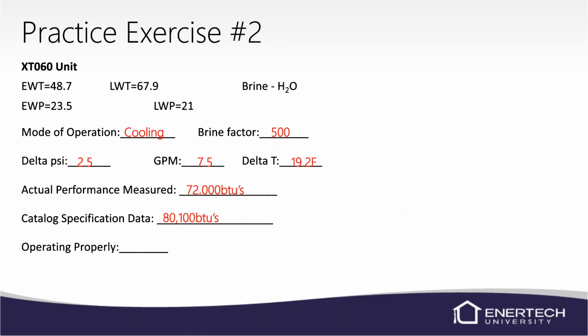So you're like, well, we're supposed to be moving 80,400 BTUs and we're at 72,000. 10% of 80,000 is about 8,000 BTUs. So 10% off is about 72,000. It's actually 71,900 and something. So we are actually within the 10% on this. We're right at 10%. So this is one where you're going to have to look and say, why did I get called out here?